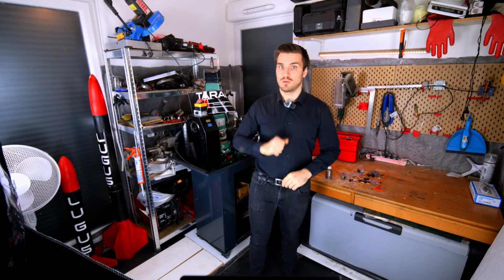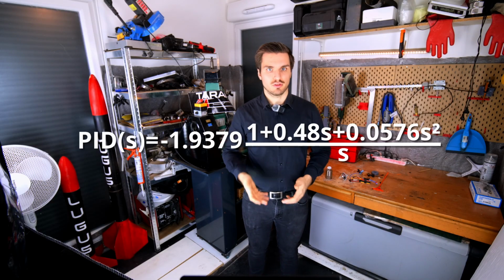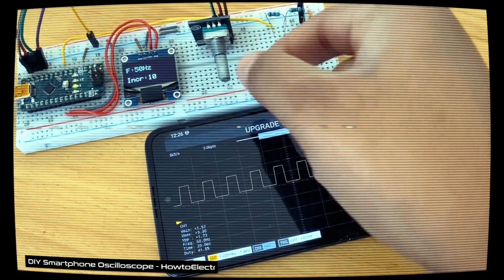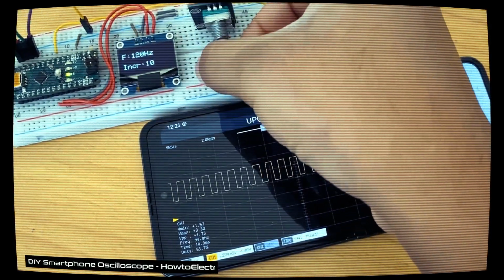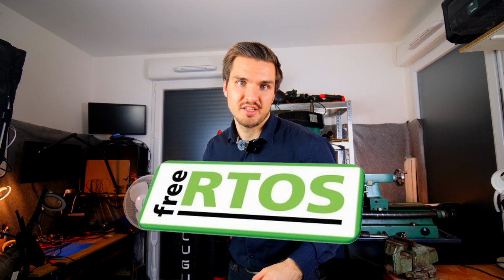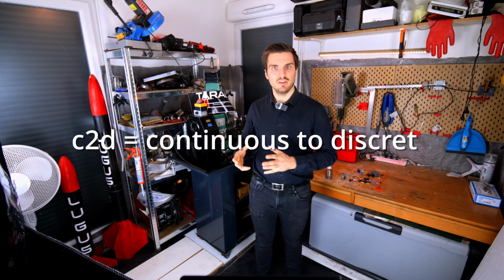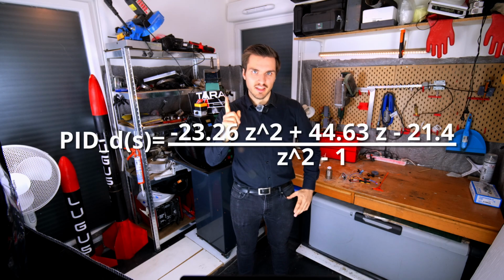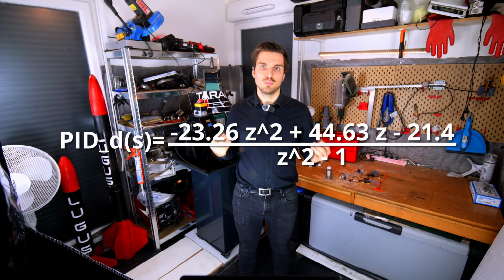Except that we have a problem. MATLAB gives us a continuous transfer function. But our microcontroller is not continuous. It is digital, so it has a frequency that is fixed and given to us by the RTOS. And that's why the RTOS is important. It guarantees the fixed frequency of your loop. So we will convert the continuous transfer function of our PID into a discrete transfer function using the c2d continuous-to-discrete MATLAB function at the frequency of the RTOS. And there, finally, you have the transfer function you want to put in the microcontroller.